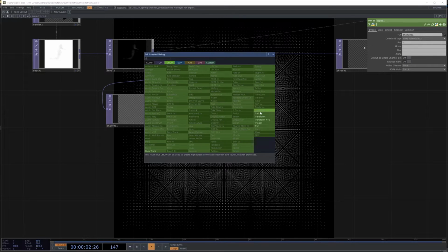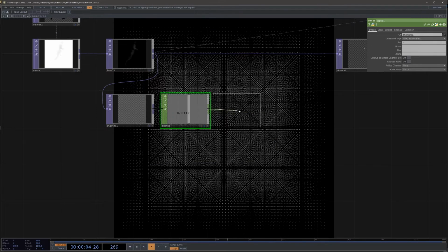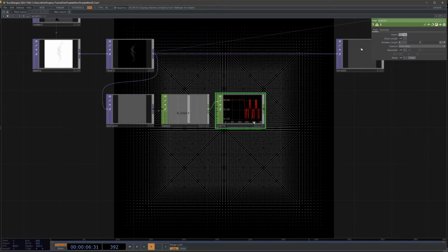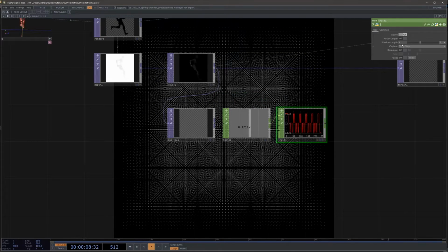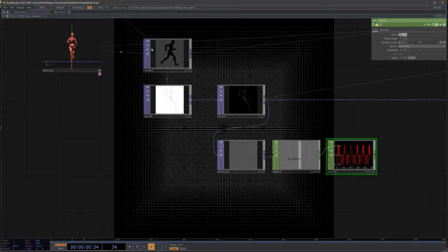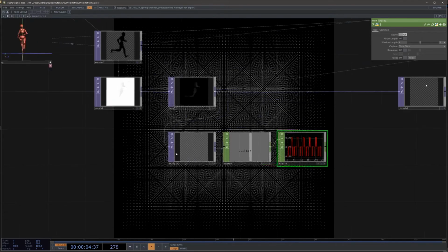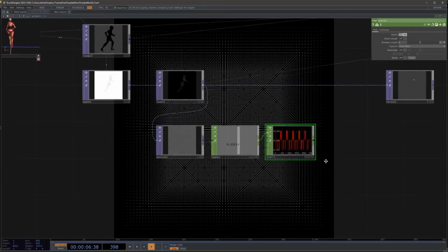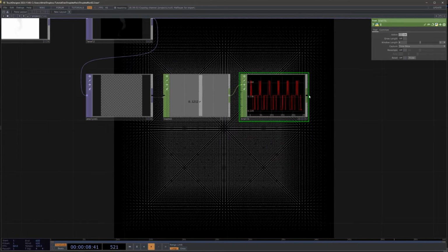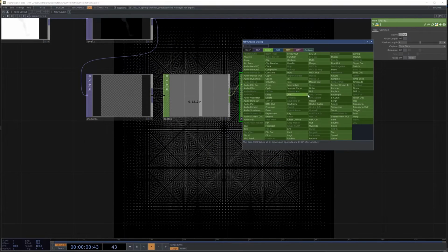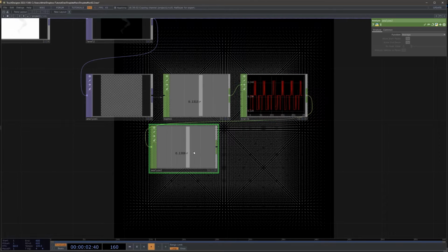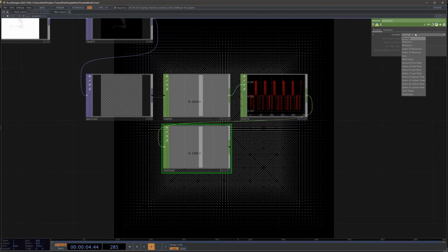And to do so, because the system is moving, I'm first going to set up a trail. Right now the trail analyzes for 4 seconds, which is plenty for this system as it's a short animation, but you should adapt it depending on your animation. And I'm going to analyze this as well, and in the analyze, I'm going to take the value of the highest peak.